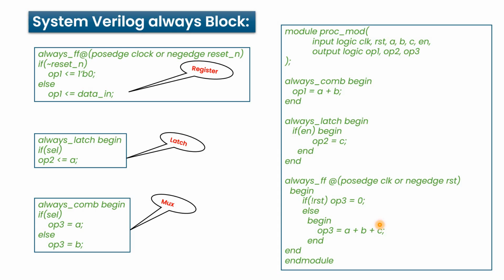So here the important issue in Verilog, which was unintentional latch inference because of wrong coding styles, gets eliminated completely. You might have heard about unintentional latch inference. That is one example I could give you at this time so that you could relate it. And that kind of problem is solved in SystemVerilog using the always_latch construct.